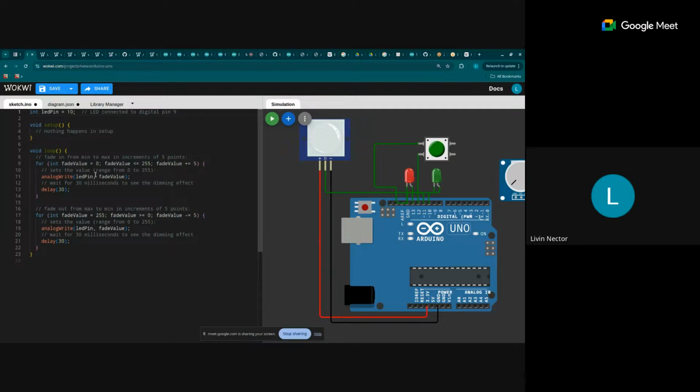So in analog read, as you see, you can get values from 0 to 1023. In this PWM, it supports values from 0 to 255, okay, which is an 8-bit value. Let's run this. Now we might see, yeah, it is fading up and going down. You can see that it is glowing in and out, right? The brightness.